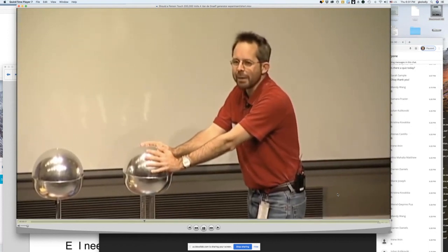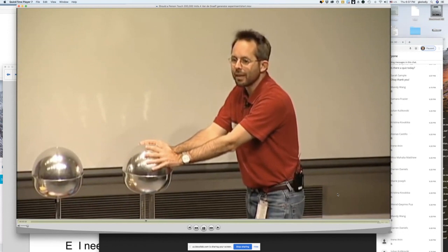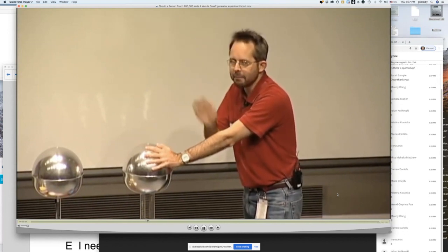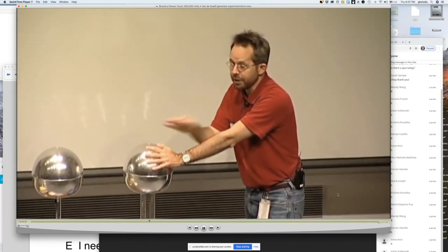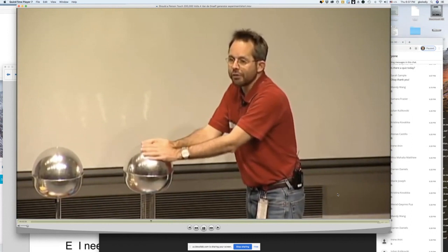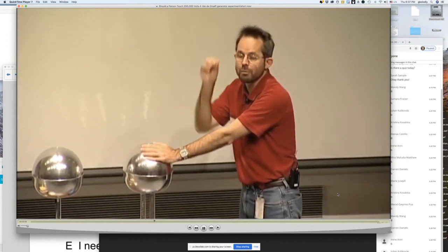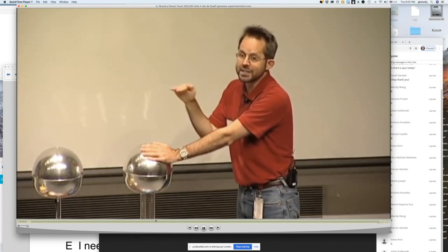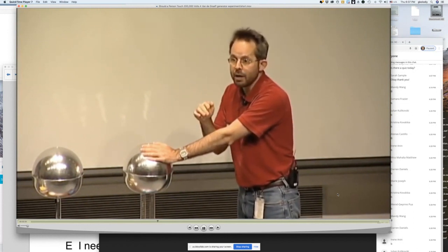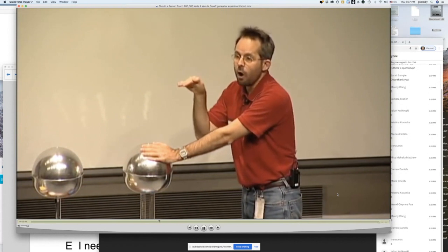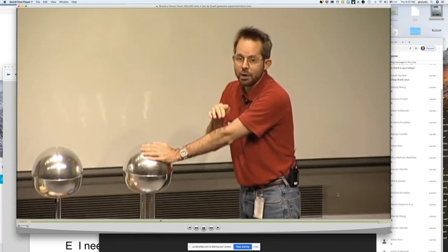Nothing. Why does nothing happen? How many volts in my left hand? 200,000. How many volts in my right hand? 200,000. What's the difference? There's no difference. Electricity flows from high voltage down to low voltage. If it's the same voltage, it doesn't move around. It's like having a bathtub full of water. If all the water's at one level, the water stays put.